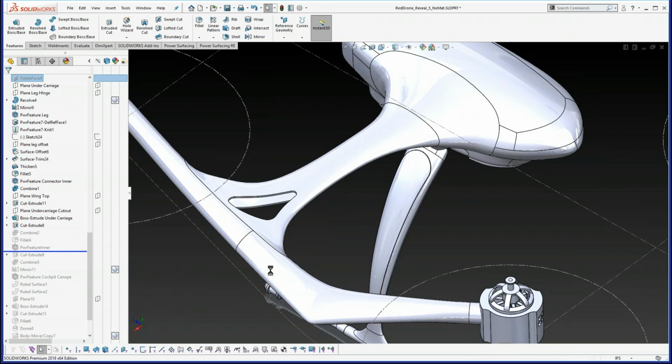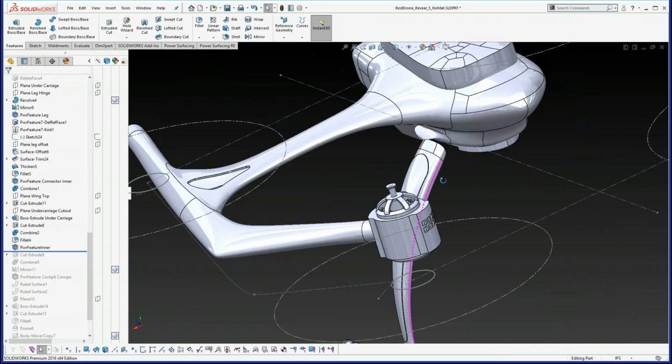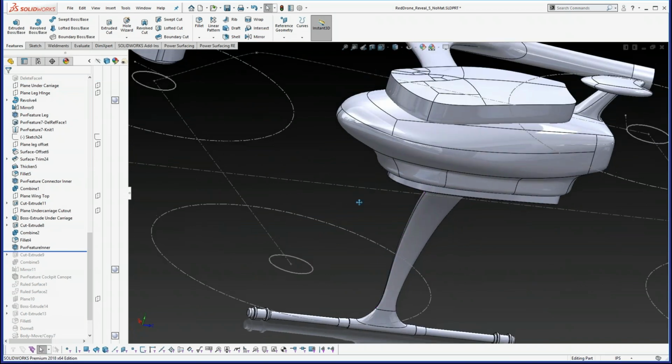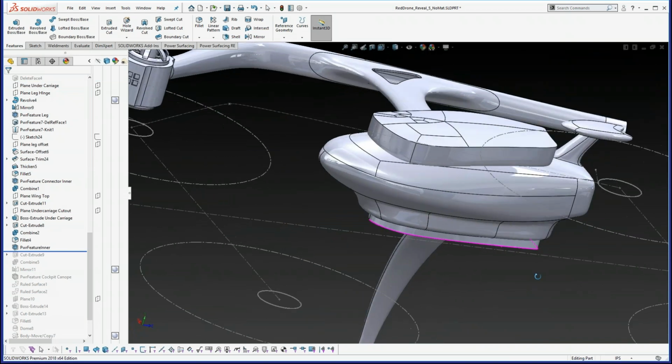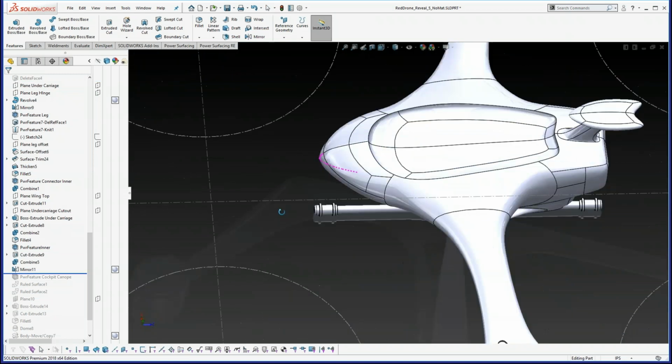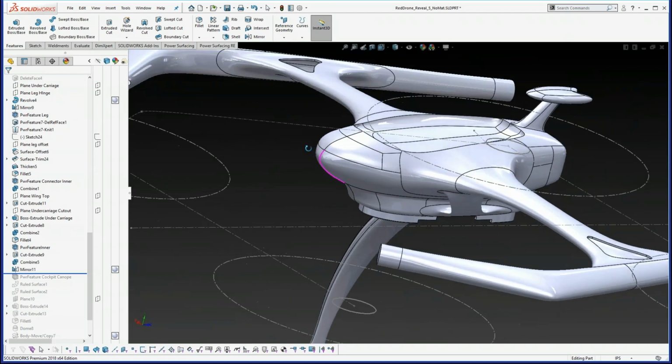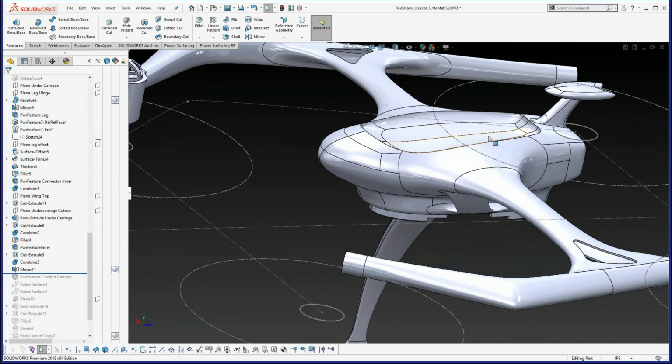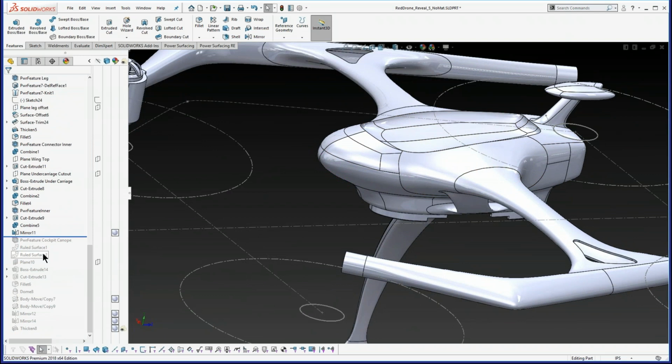And this is a design feature that was in the image that I was working from. Okay, now the next thing was I made a piece to Boolean to combine subtract for my cockpit area. So that left us with something like that. The next piece I kept as a separate piece, and I do this a lot. You might actually be working in assemblies if you have as much stuff as I do in here, but I kind of like to keep it together for demos.